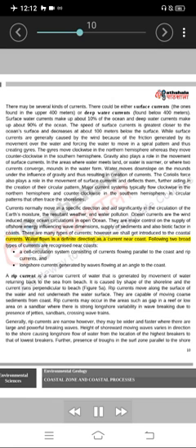Water flows in a definite direction as a current near the coast. The following two broad types of currents are recognized near coasts. A cell circulation system consisting of currents flowing parallel to the coast and rip currents, and longshore currents generated by waves flowing at an angle to the coast. A rip current is a narrow current of water that is generated by movement of water returning back to the sea from the beach. It is caused by the shape of the shoreline and the current runs perpendicular to the beach, figure 5a.